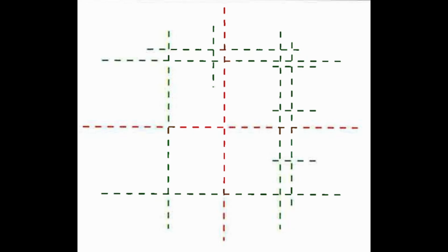The red lines in the document represent the original template crosshairs. These will appear green on your screen. Remember, use reference planes, not reference lines. Mirror planes for symmetry. Keep the original center planes untouched. Use as few views as possible to avoid over-constraining the family. These planes form the skeleton of the family.